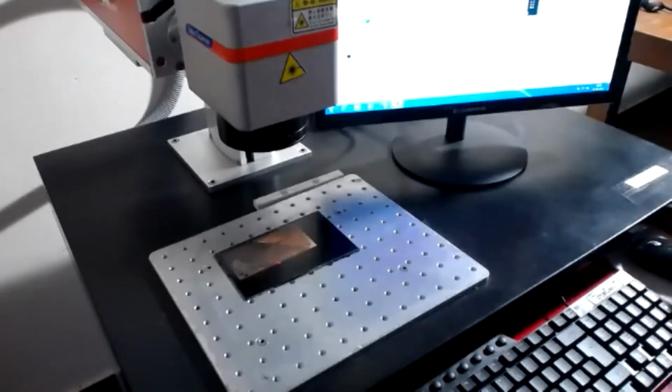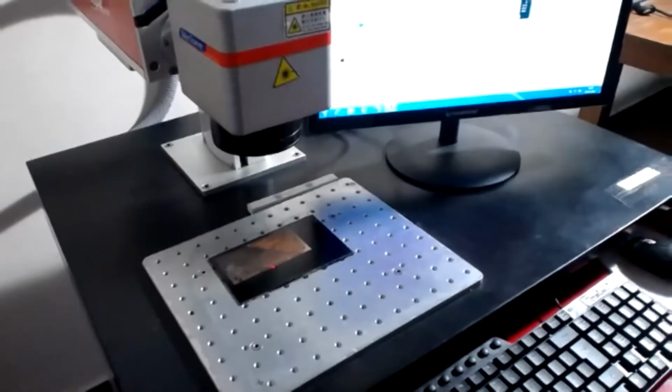So these are some of the options once you import the device. Some editing needs to be done to make the alignment and the number of engraving areas. For example, within a 1 mm area, how many engraving lines need to be done. That part needs to be given, and what resolution you want needs to be given, and the line spacing you want. Those settings can be done using these particular settings. Because it is going on, I am able to edit it. So I'm just showing how it is.